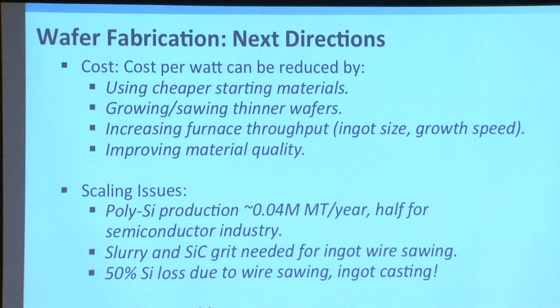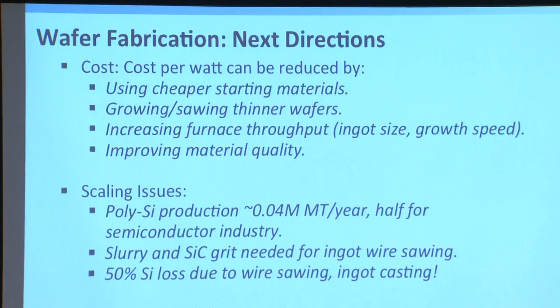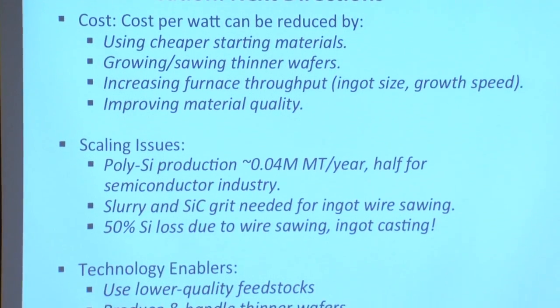more robust so that they don't snap as they're pulling through the material at about 5 meters per second in that slurry with the silicon carbide or diamond grit. Very challenging engineering as well. This second bullet point right there can be encapsulated in a larger theme called improved silicon materials utilization. In other words, the grams of silicon that you use to produce a watt peak of a solar cell. So improving that number right there.